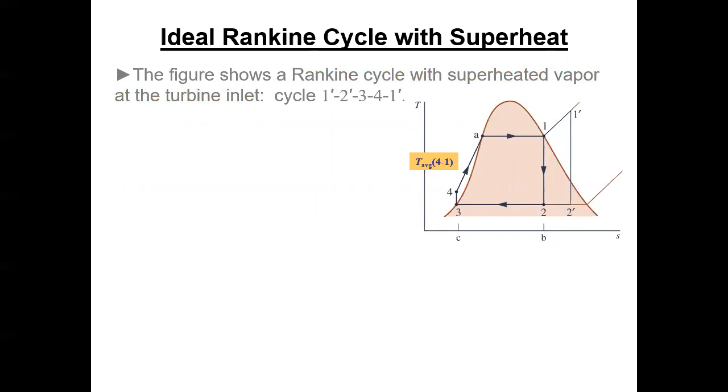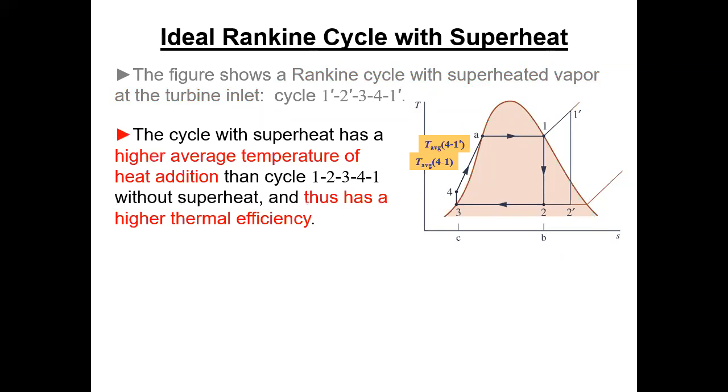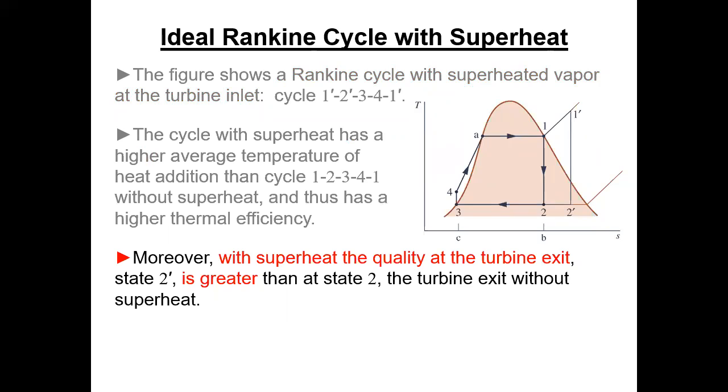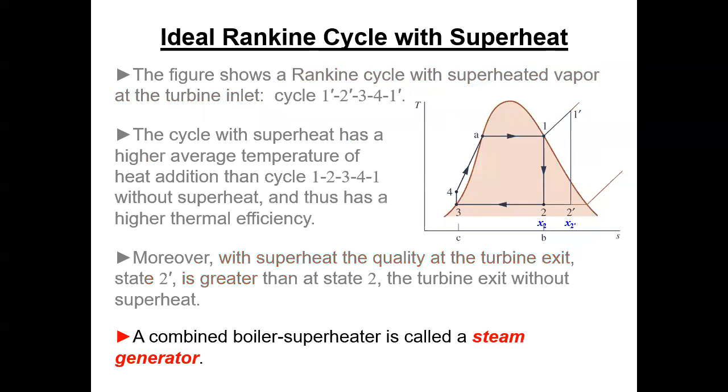And also we get an efficiency boost because of the average temperature of the heat addition. If you compare 4 to 1 versus 4 to 1', obviously that's an increased average, and so we'll get an efficiency boost as well. Higher thermal efficiency. So it's all good. Superheat is all good, except that you go up in temperature, so potentially more damaging to the materials.